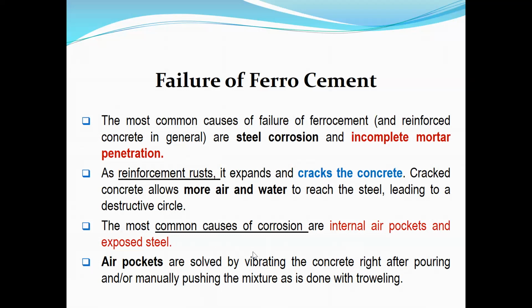Now, the issue of air pockets can be solved if you vibrate the concrete right after pouring, or if you manually push the mixture, as it is done with the help of the trowel.